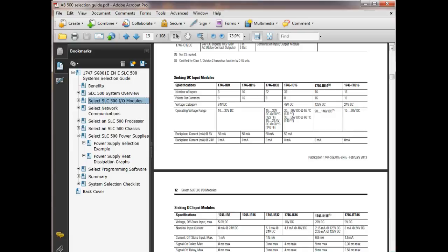We used to have to take the module analog card and open up the back of it and set these switches there all the time before we use it, because you put it in there and if it ain't programmed for that type of switch, or for the voltage levels, the type of voltage you're measuring. Yeah. Usually, some of those cards are like that.